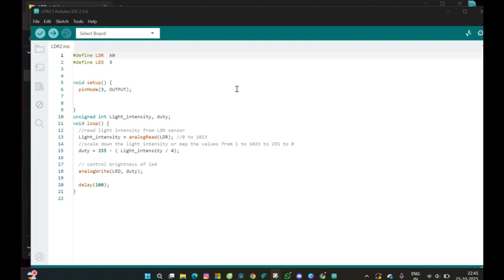In darkness, its resistance is very high. When light shines on it, its resistance decreases. This is due to the semiconductor material it is made from releasing more electrons to conduct electricity when exposed to photons from light. It finds its applications in burglar alarms, automotive headlights, greenhouse automation, camera light meters, and automatic night lights. So this is the code for the LDR system.